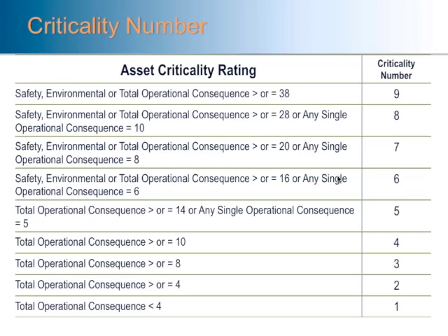The value of this exercise is then being able to take those individual discrete consequences and really aggregating them together into a collection of criticality rankings. This will allow for the generation of a criticality number. Virtually every modern computerized maintenance management system has some kind of criticality value embedded within its equipment hierarchy, normally a numeric value between 1 and 9. And you can see that a mix or a blend of the different categories can provide now an opportunity to rank individual or discrete pieces of equipment across that entire list.